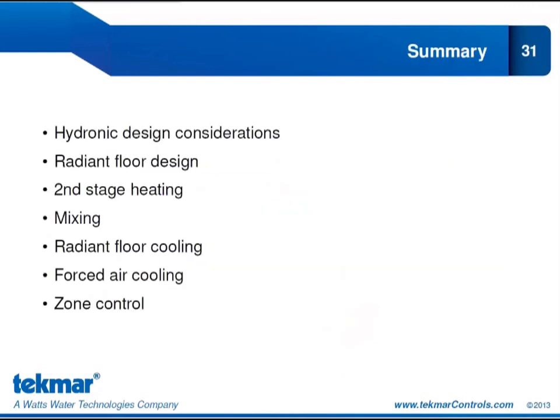In summary, this module covered hydronic design considerations, and in particular we looked at zoning and the need for low entering load water temperatures. We looked at the types of radiant floor installations that are well suited for a low temperature geothermal application and why that may necessitate a second stage of heating. If we are adding a second stage of heating, then we have installations that operate at different water temperatures, and so that drives the need to include mixing in our mechanical design.